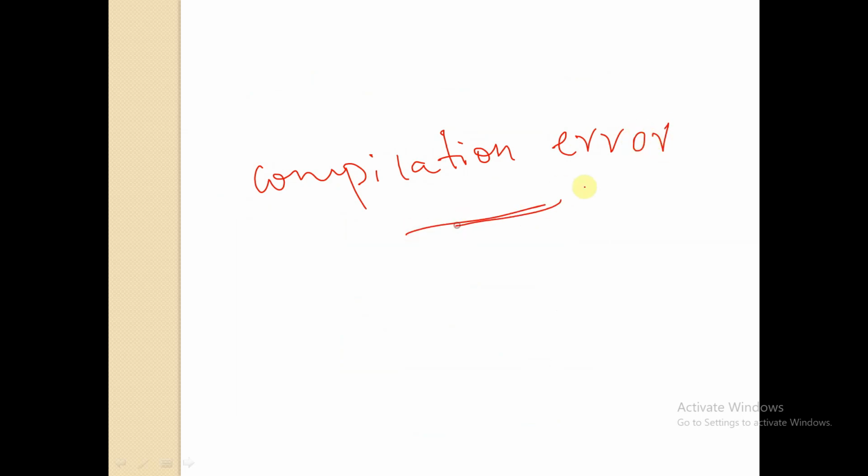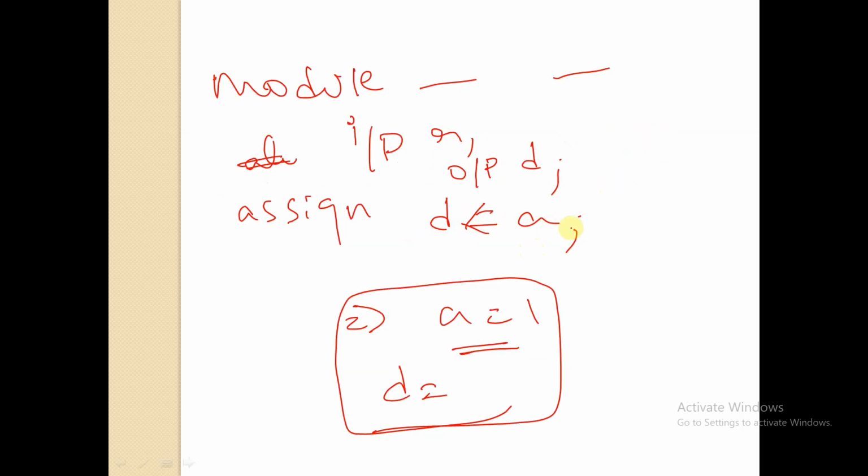Okay, so let me give the answer for this. Here also we will get a compilation error. Can you guess the reason? Non-blocking, blocking. Yes. In assign statement, we cannot use non-blocking statement.